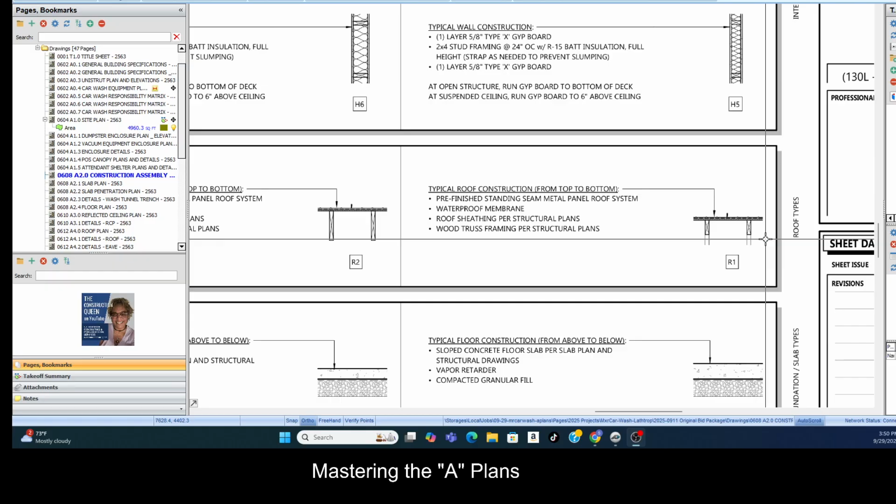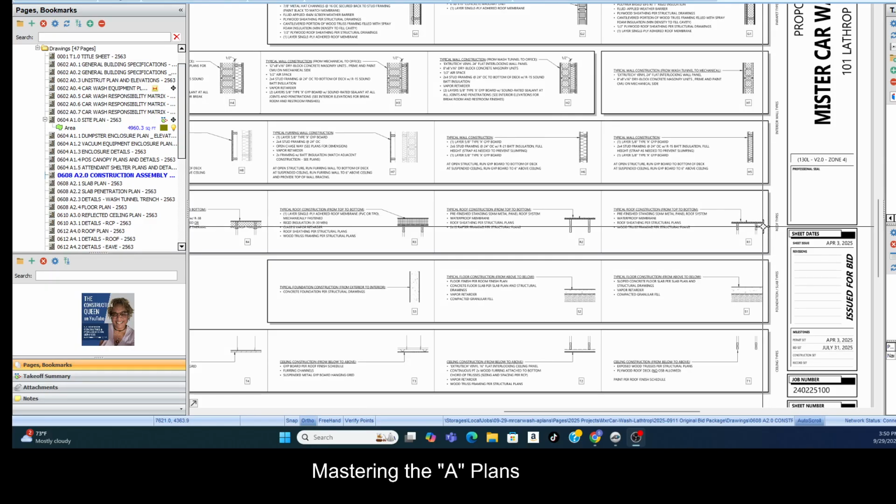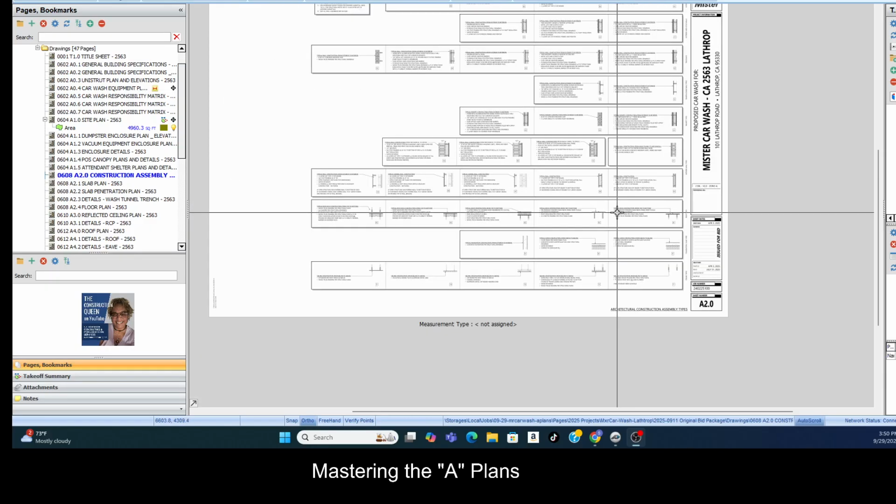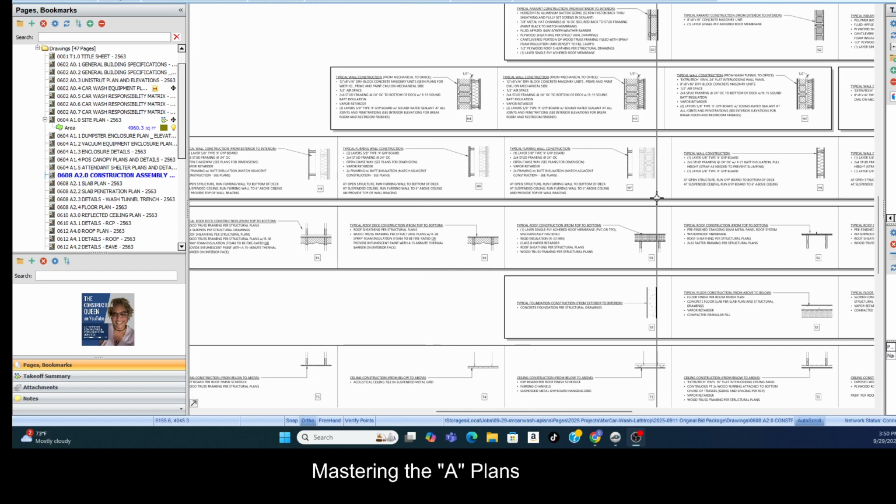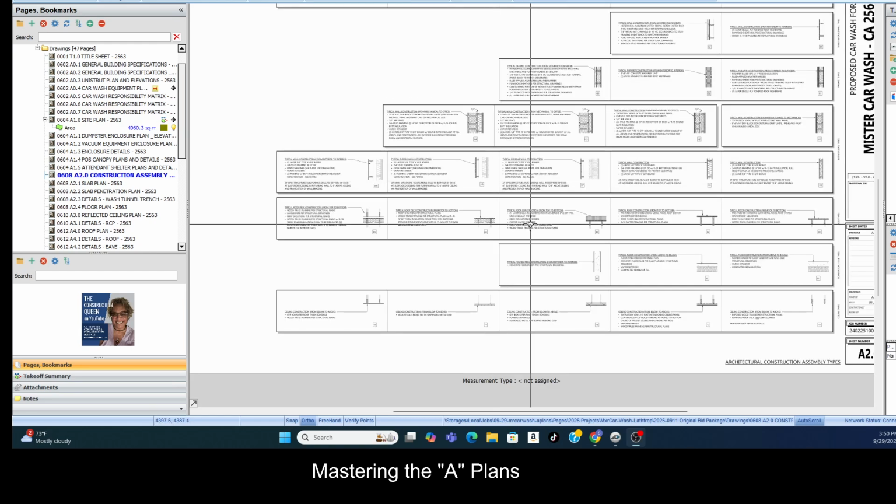So you want to make sure you are measuring accurately. That's why you need that section view, so you can see what portion of the wall is drywall, what portion of it is FRP, and all of that. So plan view gives us easy access to getting how many linear feet of these assemblies, but then we have to look at a section view to determine the height.